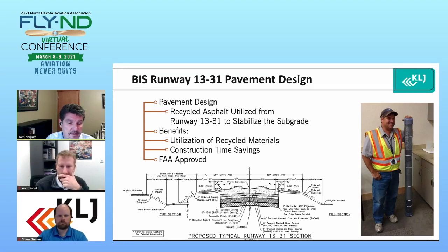We had 8 inches of P209 crushed aggregate base course, 6 inches of cement treated base, and then the icing on the cake was the 16 inches of concrete.